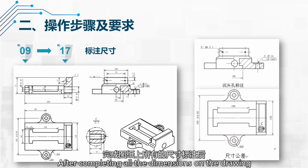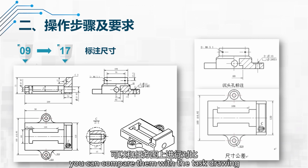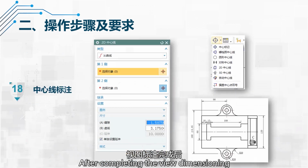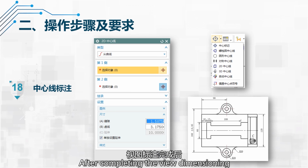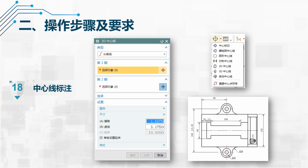After completing all the dimensions on the drawing, you can compare them with the task drawing to check if the dimensioning is complete. After completing the view dimensioning, you need to add center lines to all views, especially circles, which must have center lines.